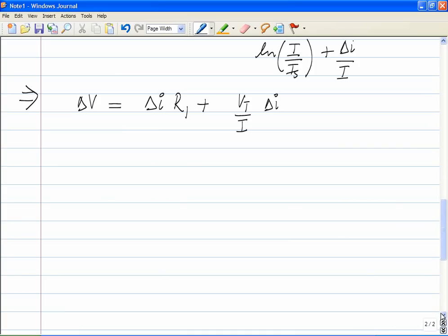And this increment in V1 causes an increment in the loop current. By writing the Taylor series for the nonlinear element, we see that if this increment is sufficiently small, where we will define sufficiently small a little more carefully later on, then the increment in the applied voltage can be related to the increment in the loop current by what kind of equation? This is a linear equation.